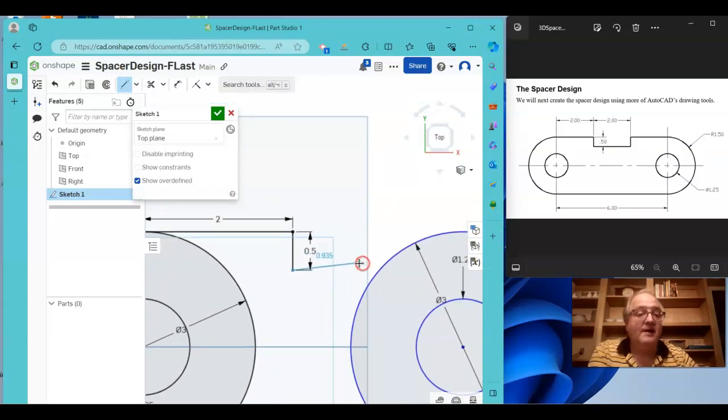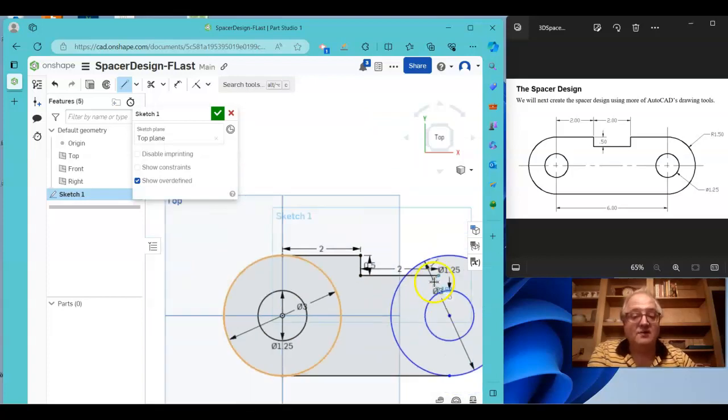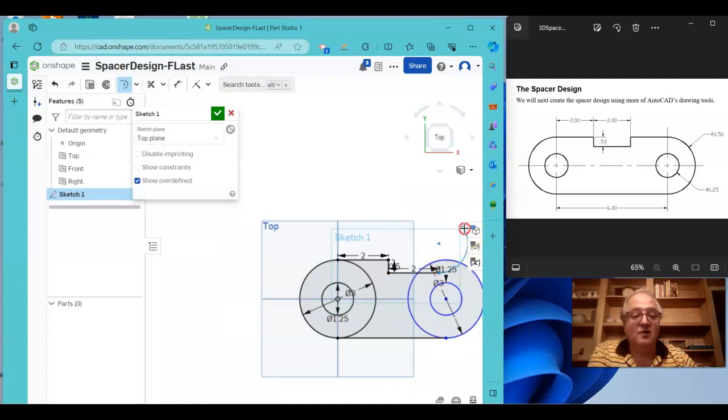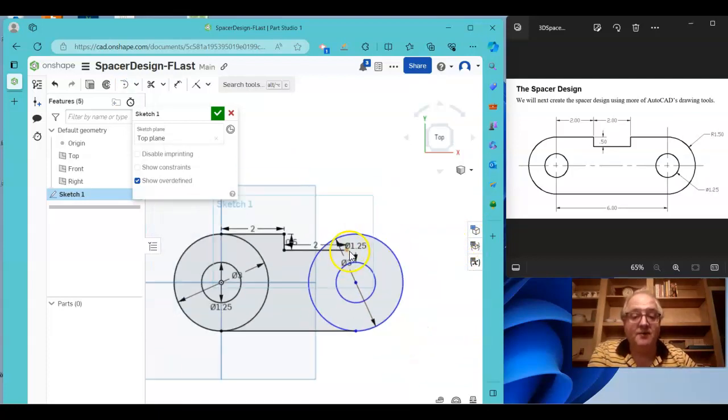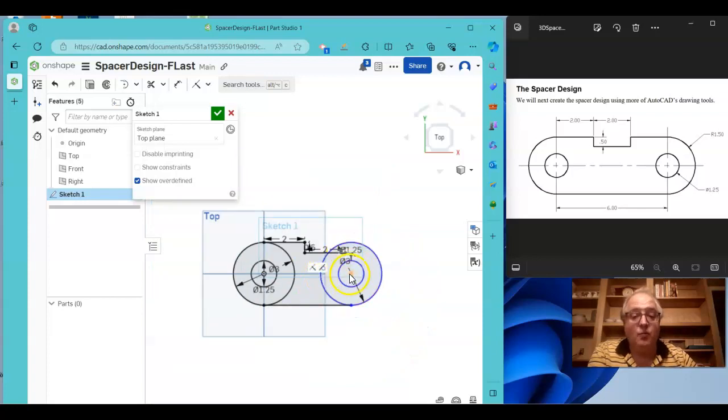And here we are on this. So I'm now making this perpendicular. See the constraint that is down in the lower right hand side of where I'm at. This is going to be a 2-inch dimension. So I'm going to left click to place, 2, enter. Notice how now we're going over too far. So I'm going to escape this line right now because we need one more thing.